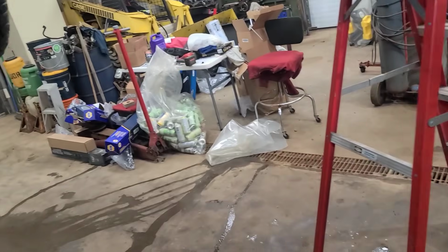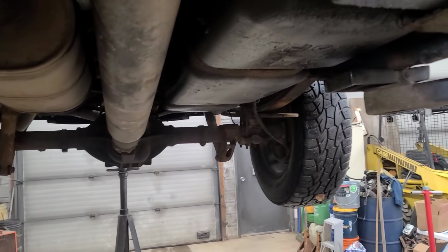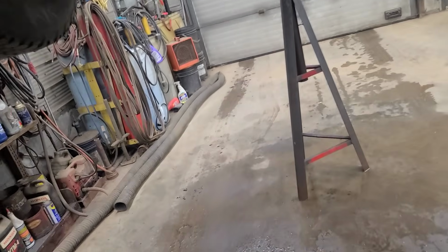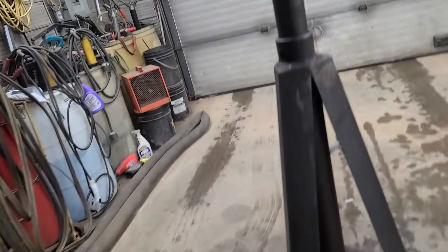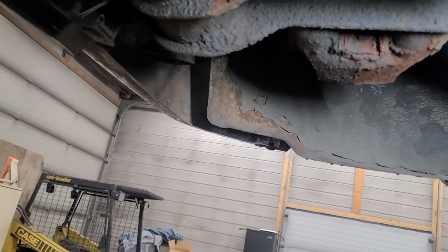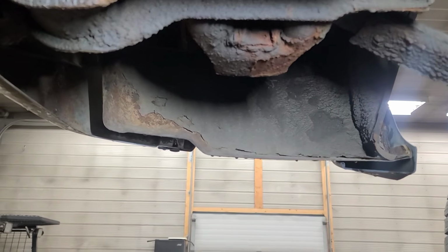So somewhere between here and the fuel pump driver module is an open. So we're going to go to the fuel pump driver now and disconnect it and short the 2 pins together, or the terminating resistor is open, because there's the terminating resistor up there. That's the terminating resistor up there.